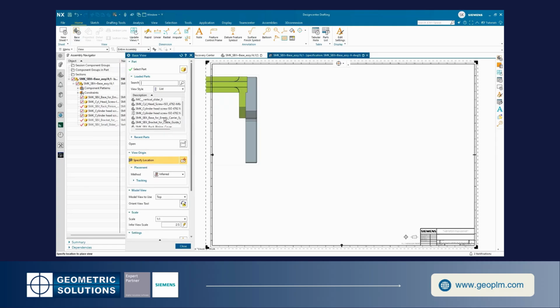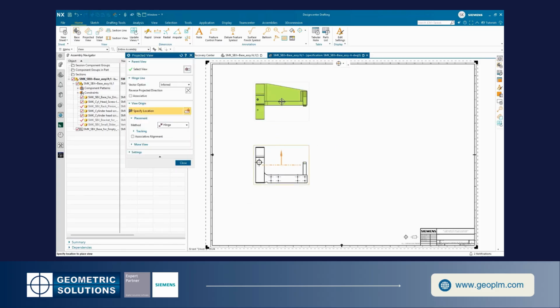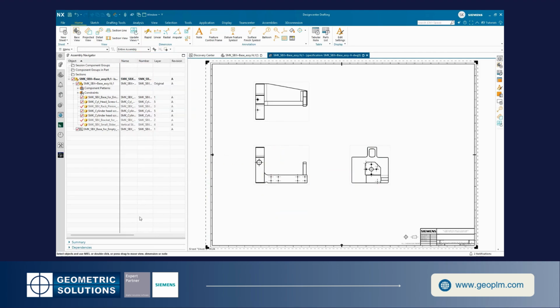So I don't want to have that tagged on as part of my build material, even though it does not show up in the build material, but on the assembly navigator it will show up. So that is that particular approach. By selecting that, now you are able to do that. Okay, so what I want to do is just do a right mouse click and remove that.